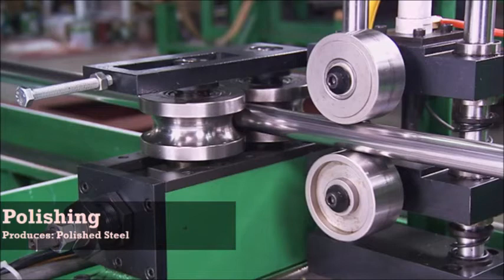Next, after the cold rolling, polishing takes place. Polishing refers to processes for improving the surface conditions of a product for decorative or functional purposes. The various techniques are abrading operations, although some plastic working of the surfaces may occur, particularly during buffing. The process causes some plastic working of the surface as metal is removed.